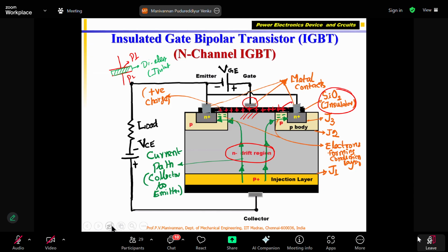But now, once you apply it, this positive charge on the top side attracts what I told you, the N region, you have electrons, correct? Electrons will be attracted. So these electrons will come and form a layer here. Correct? That will also enter inside the P region. You can see that this minus means electron. I put a green color minus. So it forms a conducting region. So the electrons are conducting. If you remove this voltage, this positive charge will not be there.